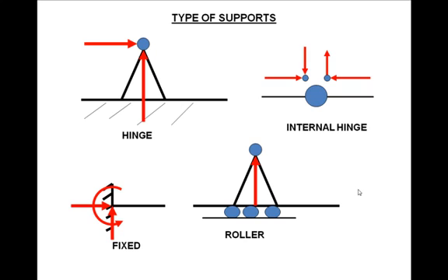Now you see, you will find this information very handy when you are actually doing applications of equilibrium of coplanar forces, which are beams, trusses, and so on. See, what happens is for every problem it's not possible to describe the way it is supported. So any support in the world can be identified as one of these 4.